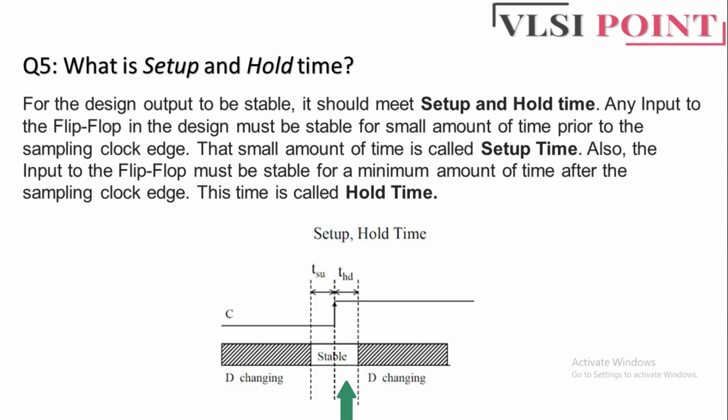Here also the input should be stable. So this is the total time where there should not be any change in our input signal. This is called the setup and hold time. If the setup and hold times are not met, the flip-flops or the registers may sample the input data incorrectly, resulting in unpredictable behavior and potentially causing errors in the circuit. Therefore, it is important to ensure that the setup and hold times are properly designed and verified in digital circuits. This is the actual meaning of setup and hold time. I hope it is clear to you.